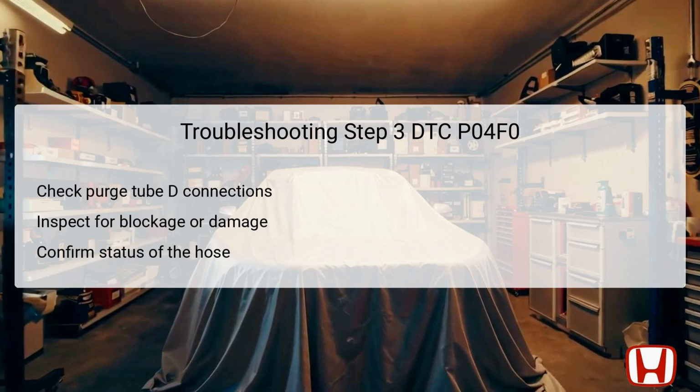If the line is in acceptable condition, you can proceed to the next troubleshooting step. However, should you discover any issues, make sure to disconnect and replace or reconnect Purge Tube D to ensure a proper seal and flow before advancing in the diagnosis.